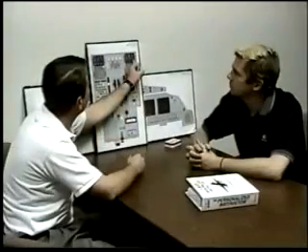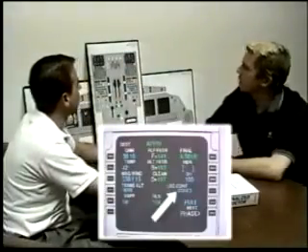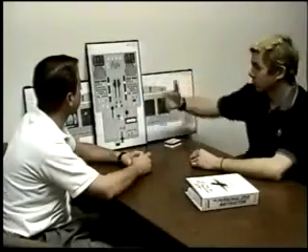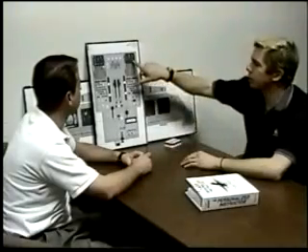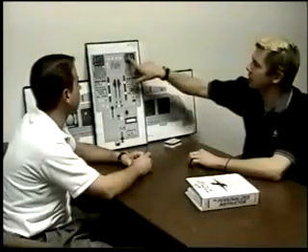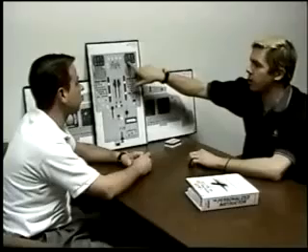Explain to me config 3 versus full. Okay? We select config full for just about every approach that we do at United Airlines. First of all, most of the landings we do are full, so we want to select full. Anytime I elect to land flaps 3 for just a reason, it's not ECAM driven. For instance, I want to do flaps 3 for proficiency, or if I suspect wind shear and I want to land in flaps 3, I'll select config 3. What this will do is it'll change VLS to a VLS for flaps 3, and then it'll allow me to slow to my managed approach speed when I'm in flaps configuration 3.